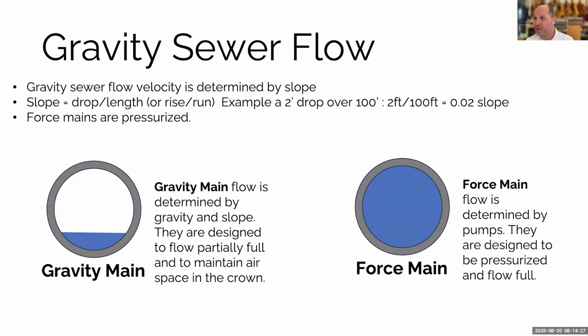But again, those force mains that we're going to talk about in the next section, those are designed to run full, and they're pressurized. And in those cases, the flow volume and velocity is entirely dependent on the pumps that we use and how fast they're running.